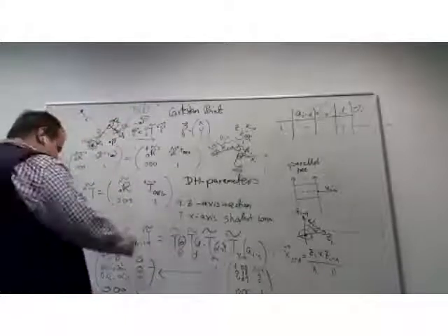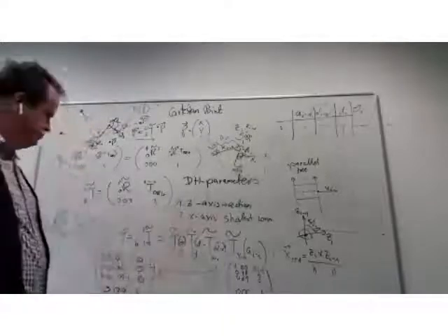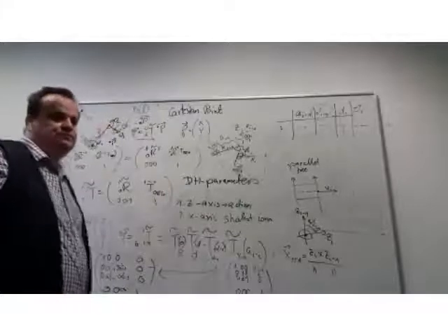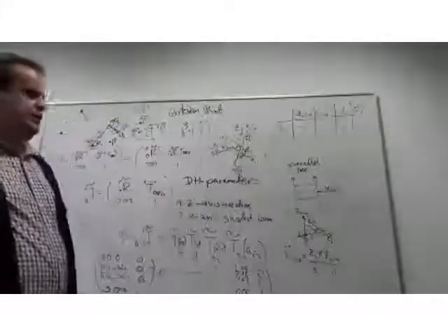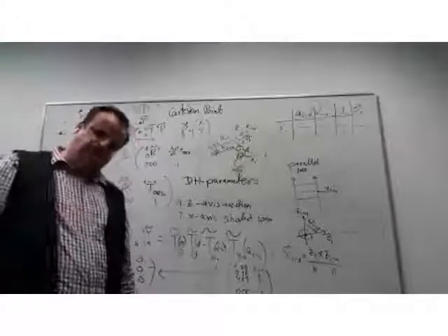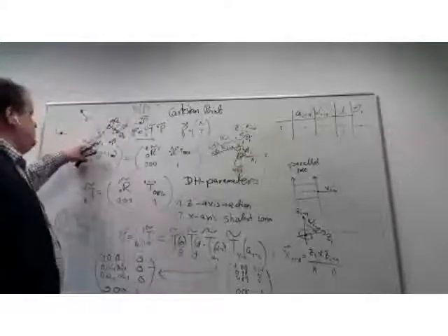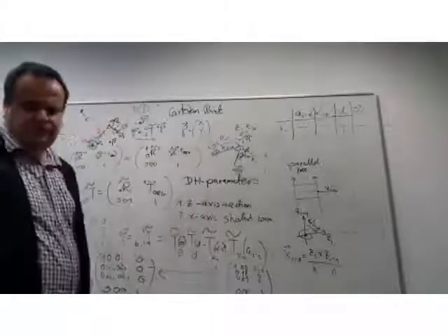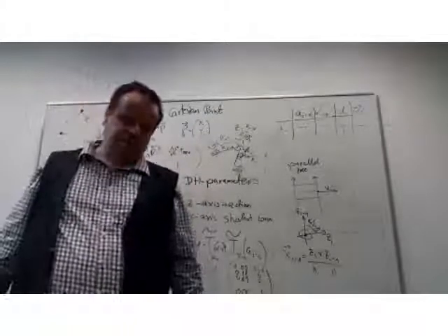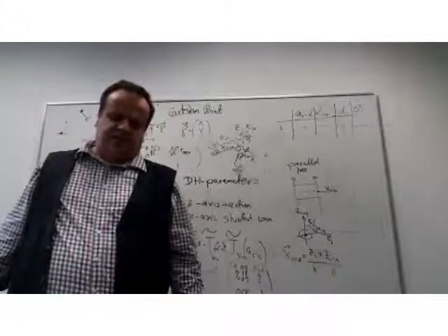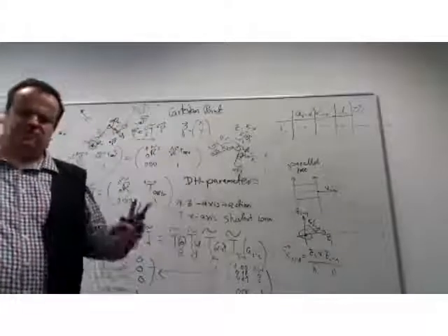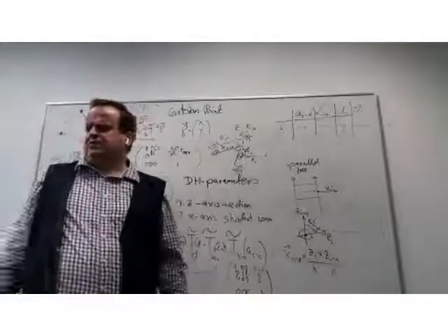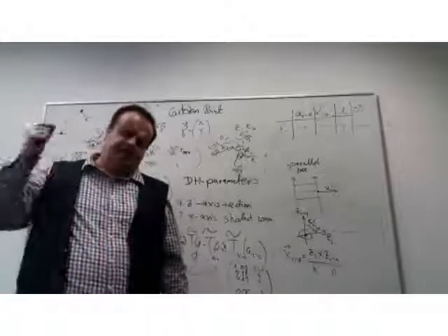You plug these values into the result of the multiplication, and you have directly the function to transform between the base frame and the wrist. In the first tutorial I will post today, we will be practicing exactly this. We will be looking at 12 different robot structures and assigning DH parameters to them by defining the z coordinates first.